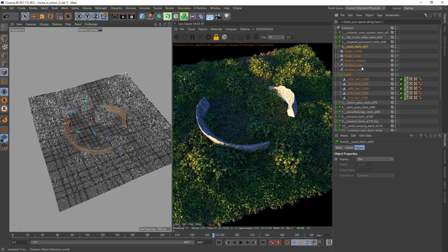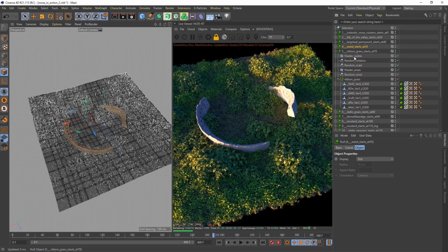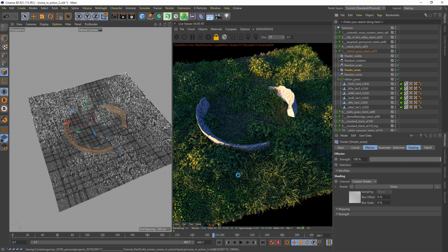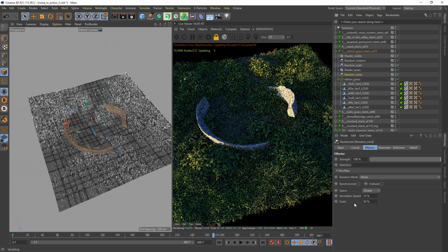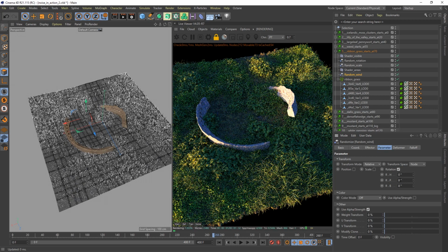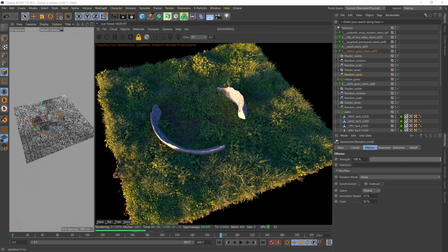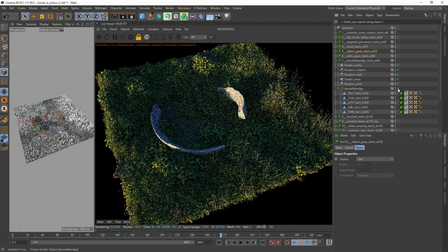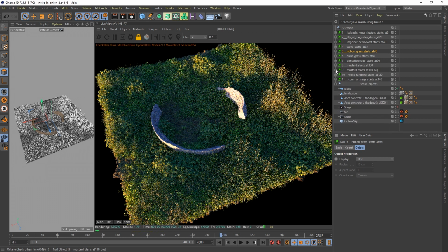By now you should get a little bit bored by these explanations. This is kicking in at 55. Just another layer of clones. So now we could go fast here. It all works the same, but I think the shader areas, they just use a different noise to decide where things should appear. And also the wind varies a little bit here. So I guess you can see this has 8 and 8 as a rotation angle, and an animation speed of 12 and a noise scale of 50. Alright, so I think I just can activate all of them now, and the system is always the same.